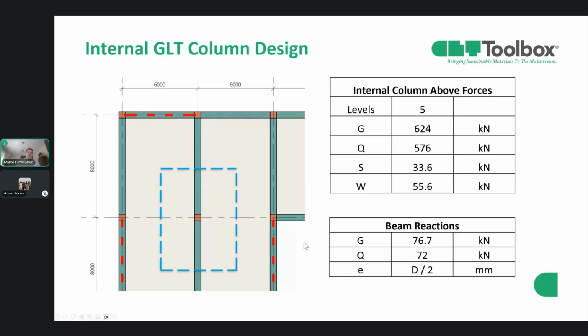Before wrapping up, I'll also take you through the internal GLT column design, but again, in case of fire. So this is just a preview from previous webinars where we have loads from above that are acting on the ground floor column. So we have levels from above, reaction forces for all the loads, and we also have the beam reactions that are acting on this column.